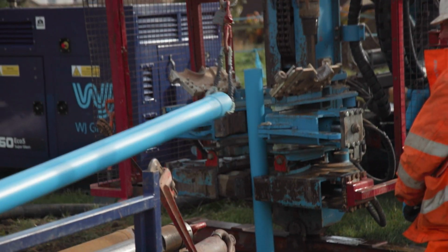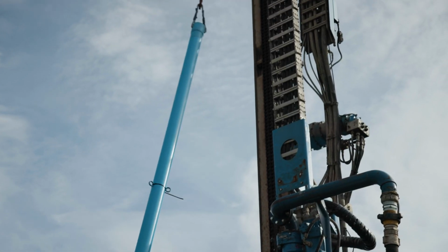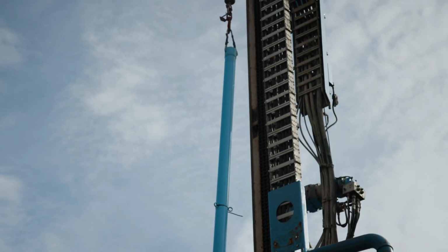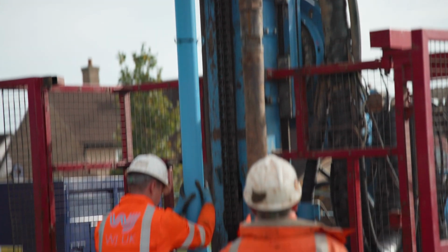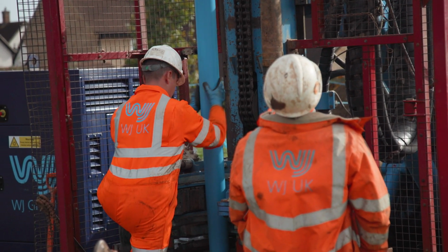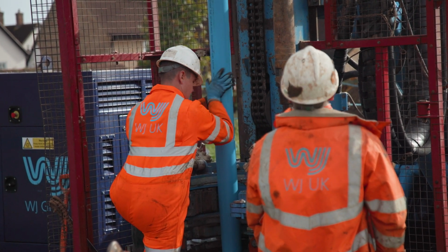The position of the well screen needs to be determined to match the findings from drilling. Some pieces of casing and screen can be assembled prior to carrying to the rig, depending on the mast height. The casing and screen column should be lowered into the hole as soon as possible after removing the drill string.